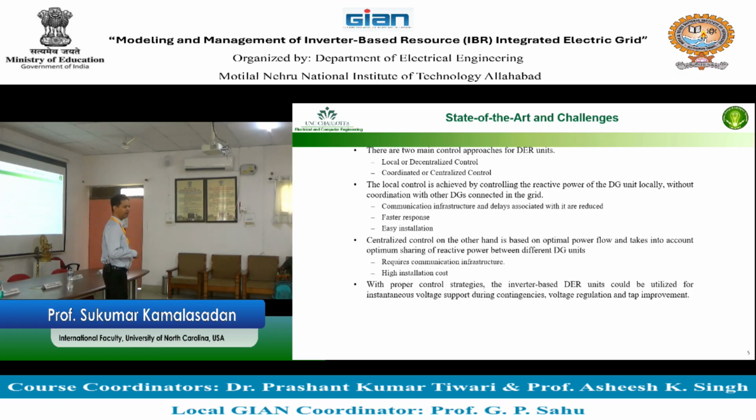So reactive power management on the DR unit can be local, and that is called decentralized, which means you're having reactive power management at points that are not related to the central substation. Or the reactive power management can be coordinated or centralized. So two different ways, the same as with active power too. Centralized control, everybody knows centralized control. From a central location, a command comes, and based on that command, the local devices have to work.